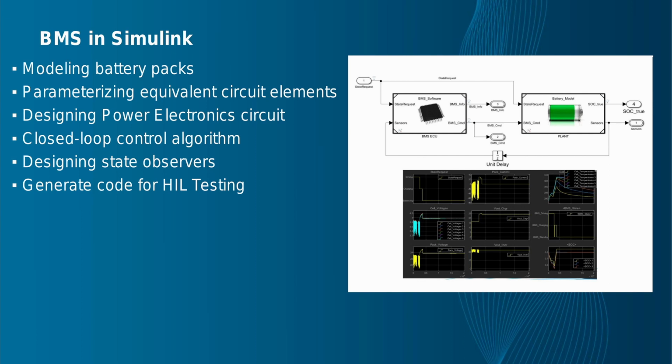It aids the designing of the power electronic circuit that connects the pack with the controls, helps with developing closed-loop simulation, closed-loop control algorithms for supervisory logic and also fault detection, designing state observers for state of charge and state of health estimation, and by using Simulink, engineers can exercise the battery management system over a range of operating and fault conditions before committing to hardware testing.